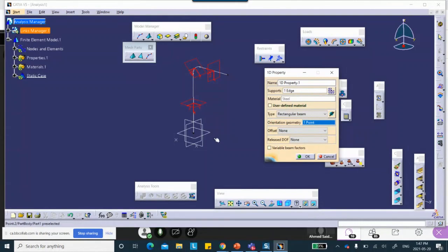So the way it works is, my X is always along the path. That's the way CATIA works. The X is always along the path when it comes to this dialog box. Then you drop a perpendicular from this point that you select to the path. Therefore, this point cannot be on that path, because you're going to drop a perpendicular. That perpendicular is called direction Y. In fact, you can see it.